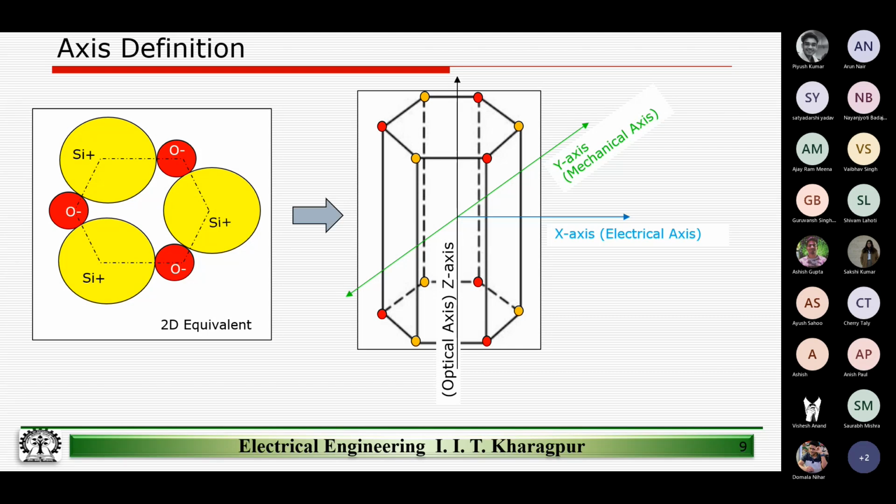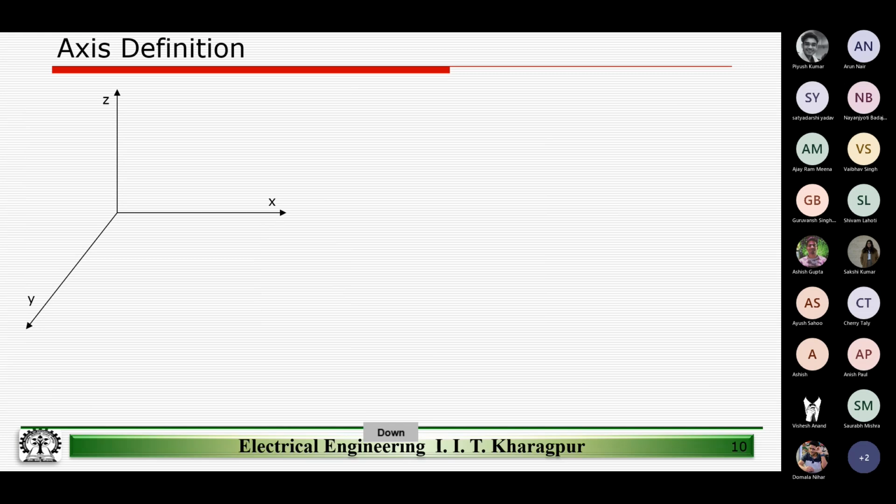there's no electrical source associated with the crystal. We are just saying that we have chosen a crystal and we are applying a force, and the net charge will be 0, right? So let's keep that in mind. And with that, we said that we'll define 6 axes. The x-axis as axis 1, the y-axis as axis 2, and the optical axis as the z-axis, which is the third axis. And then the angular axes around which the shear force will be talked about. The shear force is on the axes 4, 5, and 6.